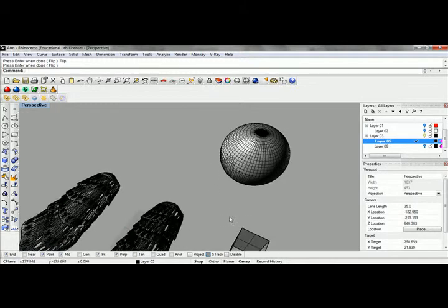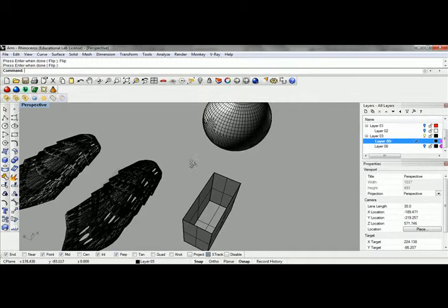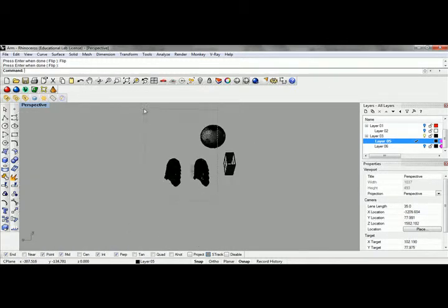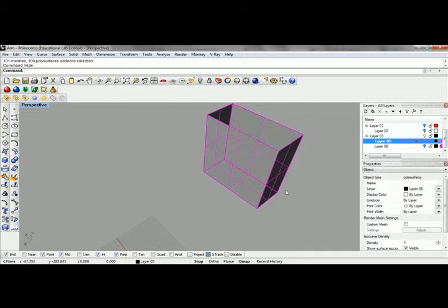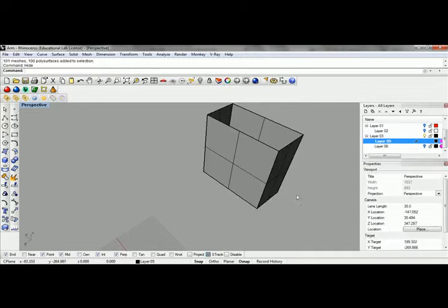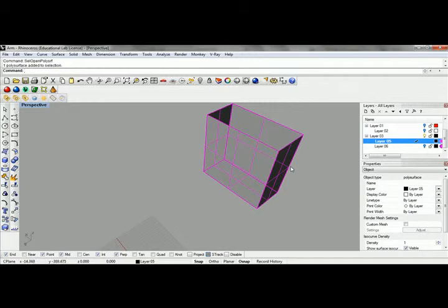The other thing is, back here in your polysurfaces, I'm just going to go ahead and hide this for now. If we don't know where the holes are, say we do a select open polysurface, and it gives us this opening, and we know it's this geometry, so we can isolate it easily, but we can't easily figure out which edge it is.